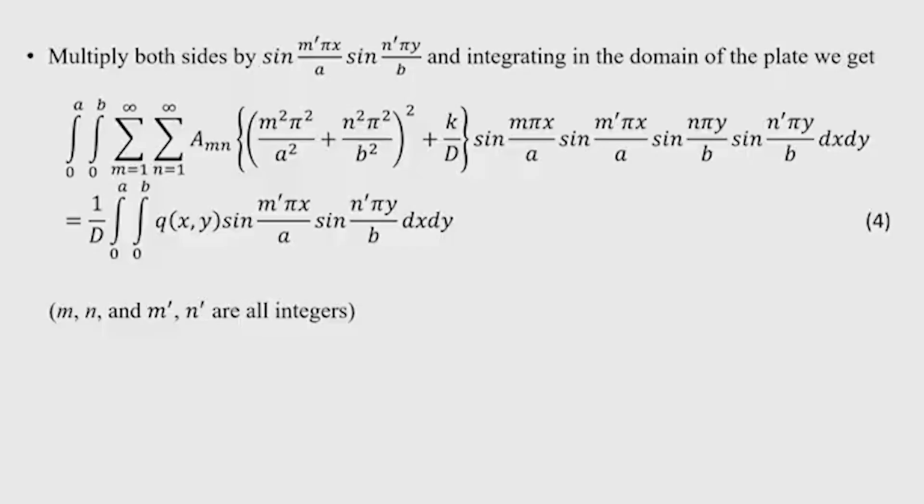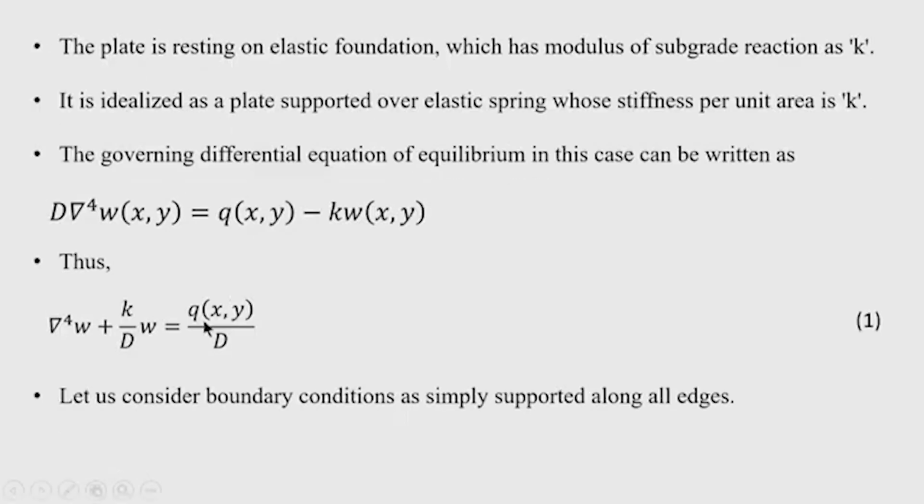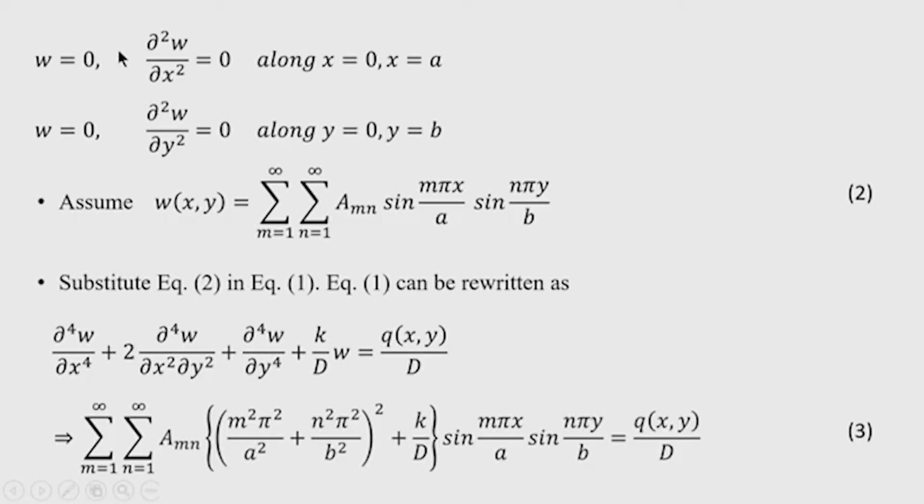For example, if I consider the foundation which is acted on by column load and by this upward soil pressure, then I can treat the foundation as fixed at the column and the edges of the foundation may be taken as free. So, in that case the boundary condition will be different. Okay. Now, let us see the boundary condition in our case, the simply supported boundary condition.